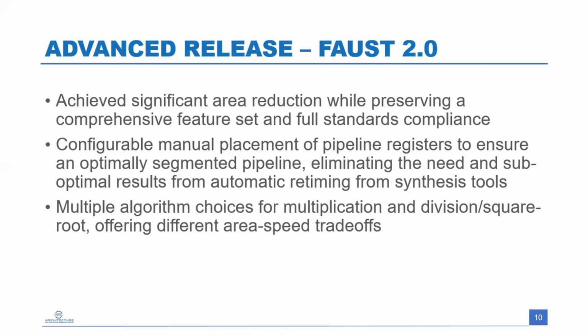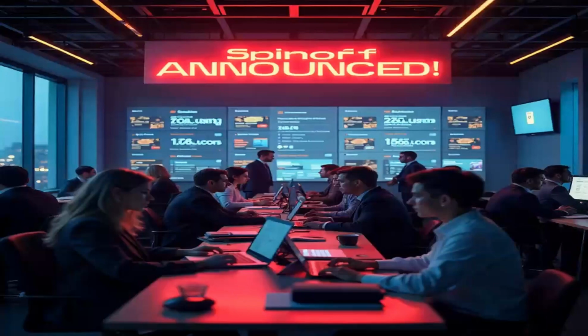Also with implementation of manual pipelining, some of the issues that we found in the initial phase disappeared when we introduced manual pipelining methods. Also, we have been able to more closely control the handshaking of the interfaces between the floating point unit and the vector unit itself.